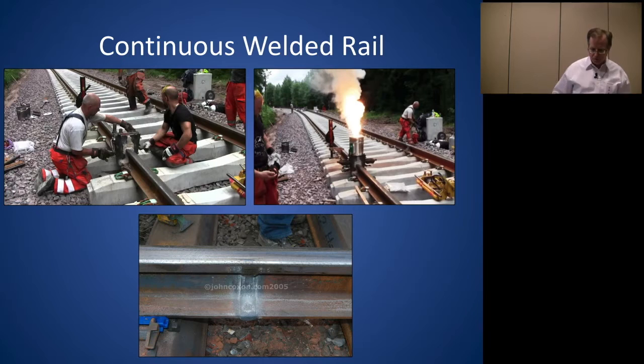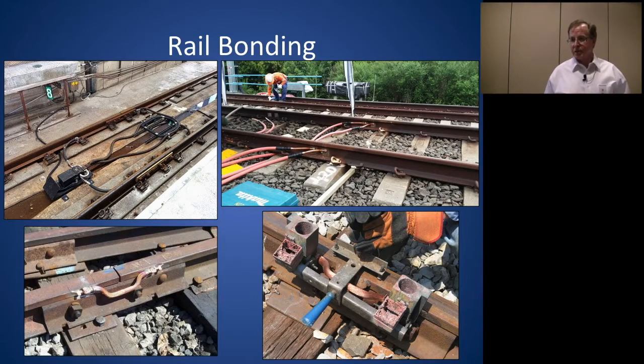You can also do electrical arc welding as well. Yes, it is. There have been some studies where they're concerned about cracking around the welds from the heat affected zone and things like that. So some people are getting away from the exothermic welds and going with the electric welding.